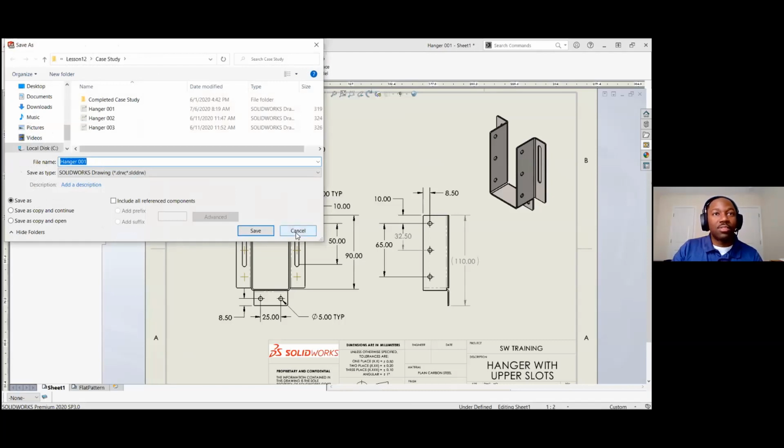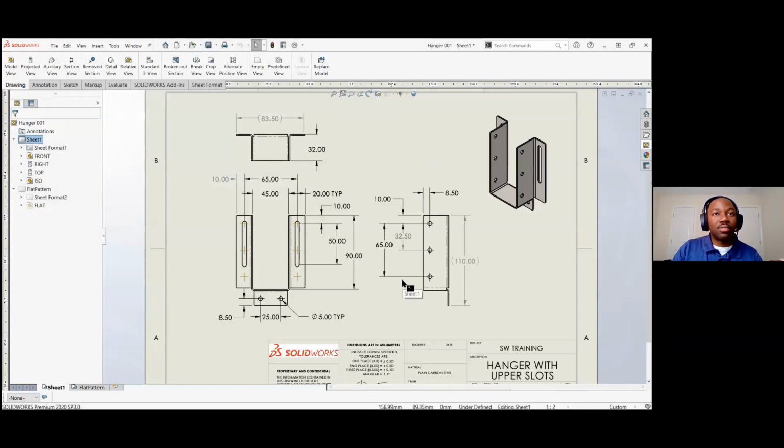Yeah, what I always tell people is just go ahead and do a Control-C, Control-V of the drawing itself, because drawings are one of the things that we can copy without it really messing up any of the references. So then you've got, say, a hanger 1 and a hanger 9 drawing, but they're exactly the same. So if you click on to open the hanger 9, but before you actually open it, you hit the references button and then point it at the other guy. You can change the references. And then once you get it all opened, you save it and it'll update the changes.